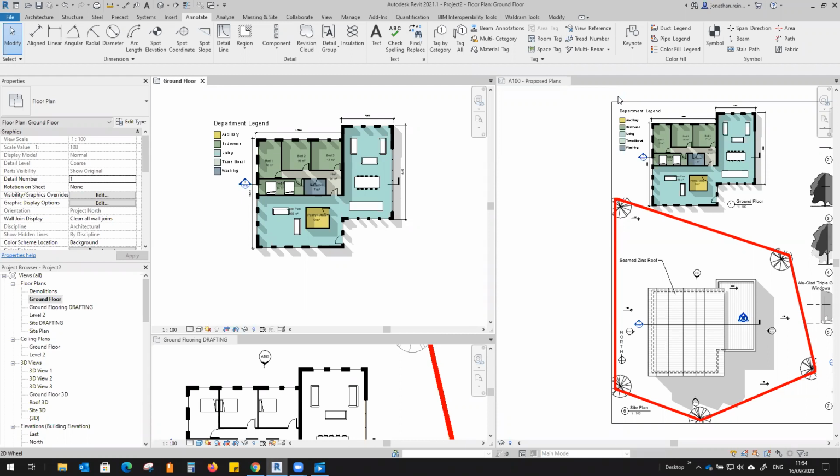So I think we had one or two more, and then we'll probably have to call it quits. Can you have the shadow from the whole building projected onto the plan rather than the cut building? From Claire, I'm just thinking what that might mean. Oh, talking about the shadowing that you've got in your roof plan. I understand. Yes, that will in fact only appear in your roof plan as long as you haven't hidden the elements. It won't work in the cut section. I understand what you're saying there. Okay, let me know if that's okay, Claire.